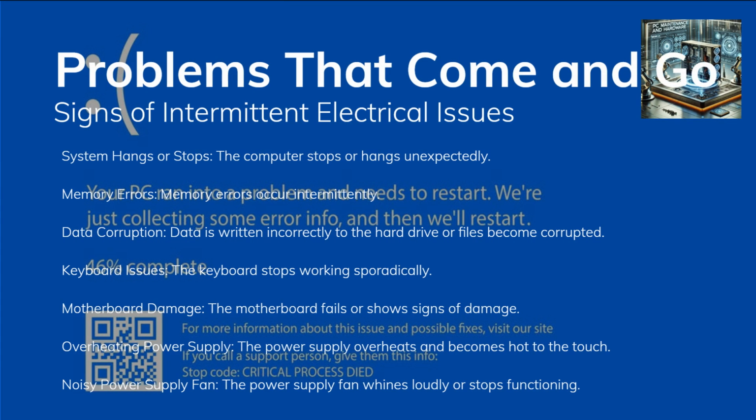Intermittent electrical problems can be tricky to identify, but here are some common symptoms to watch for after the computer has booted. The computer might stop or hang without any clear reason. You may see random memory errors, or data could be written incorrectly, leading to file corruption. The keyboard could stop working at odd times. More severe issues include motherboard failure or damage, an overheating power supply that becomes hot to the touch, or a power supply fan that becomes noisy, whines, or stops working altogether.